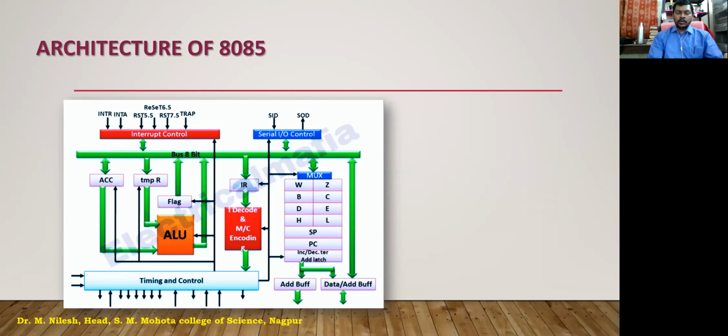Lastly we store the last instruction, which is supposed to be the halt, or if you want to put it in an infinite loop, then we'll have a loop. After feeding the program, we have to give the first address of the memory location, that is, where the program is fed. When we have started with 6000, this is the first memory location where the program is fed.